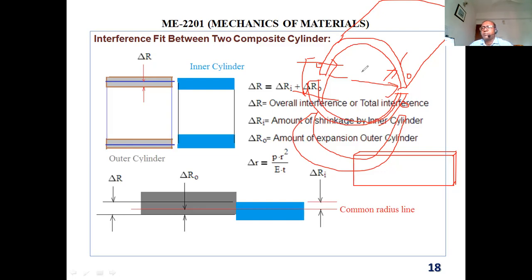Like this one, we overcame it. What we did, we sent it to the heat treatment plant. So, radius is increased a little bit. Then again they put a pressure from the outside to reduce the radius. They heat up the parts a little bit, then cool down at room temperature slowly. Then they say there is no change in diameter if you keep the parts for the next 20 days. Okay, that's how we overcame it.